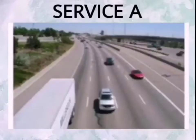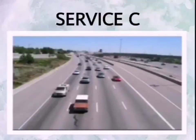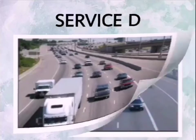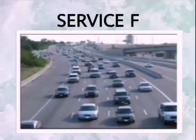Service A represents free flow conditions where traffic flow is virtually zero. Service B represents reasonable free flow conditions. Service C delivers stable flow conditions. At Service D, the highway is operating at high density levels but stable flow still prevails. Service E represents the level at which the capacity of the highway has been reached. And Service F describes a state of breakdown or forced flow with flows exceeding capacity.